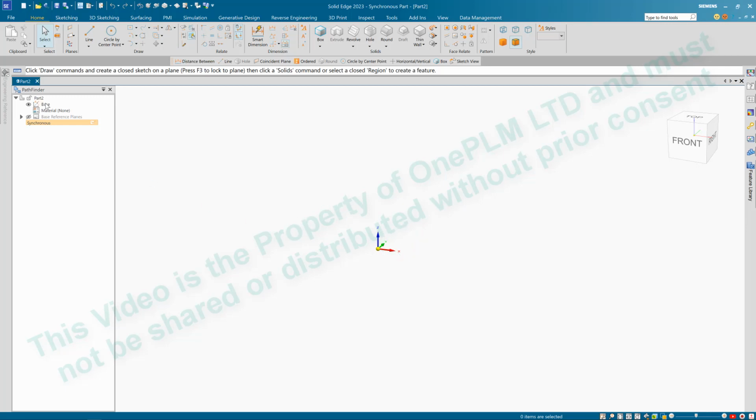We can see on our list here we've got our base system, our material and reference planes as well. If I expand that, I can hover over and we can see our base reference planes. These are our sketch planes, a piece of paper that we're going to draw on.